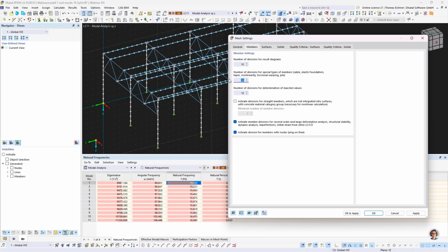And I'm going to take it simple. I'm just going to pick one here. I'm going to leave this option on. That's perfectly fine. And with that, we will get rid of our plenty of in-between FE mesh nodes. It's also to be said, as you can see, only the beam members have those mesh nodes. The truss members do not. Internally in the program, we already implemented to simplify those truss members by 2 points, since it's just not needed to have more, also for static analysis.